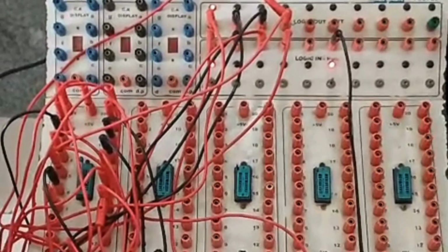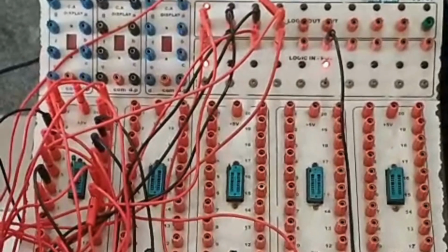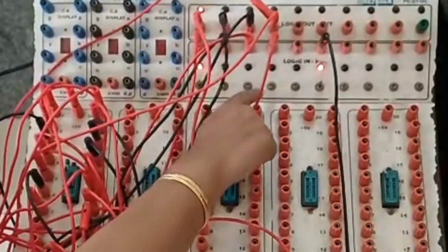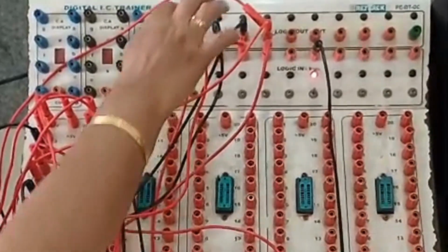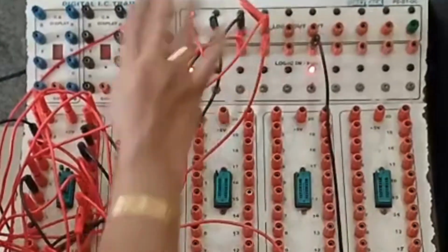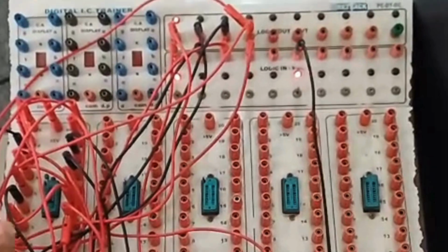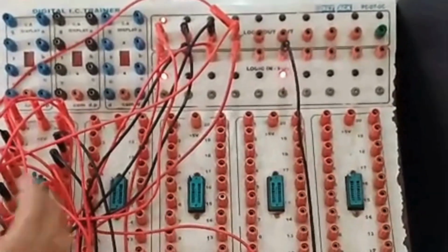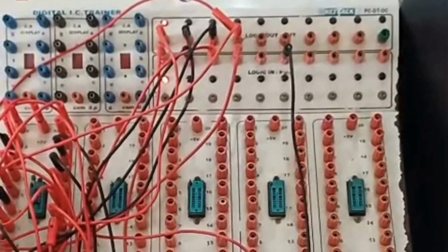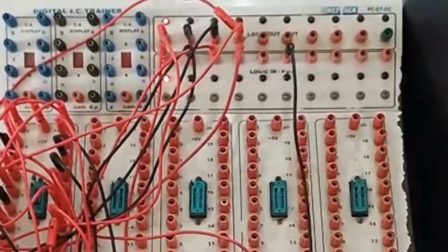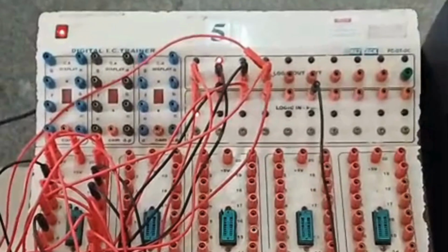As soon as the clock pulse is applied, whatever data we have loaded is going to appear along the shift register. We have loaded the data 1000, and the same is reflected on the shift register. Now this data should move to the right because it has to work as a ring counter. So let us change the mode to 0, because now the data has to move serially, and give the clock pulse. You can observe now the data is 0100.